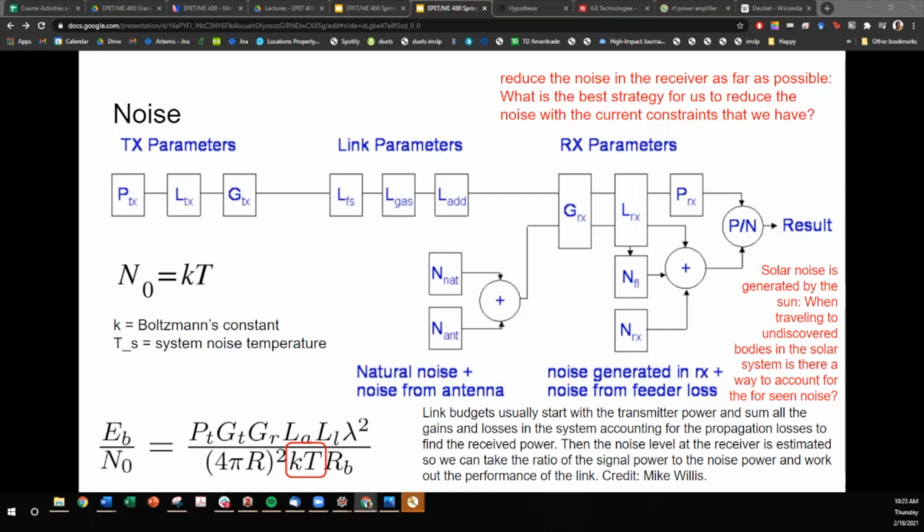So amplifying the actual signal seems a lot more straightforward. You pick an antenna with a better gain pattern, you transmit at a higher power, and then there are other modulation schemes that you could also go after. But reducing noise can be hard. Maybe you can also choose an antenna with less noise built into the electronics. But I think the big picture answer for this question, what is the best strategy, is to reduce noise or amplify the actual signal.